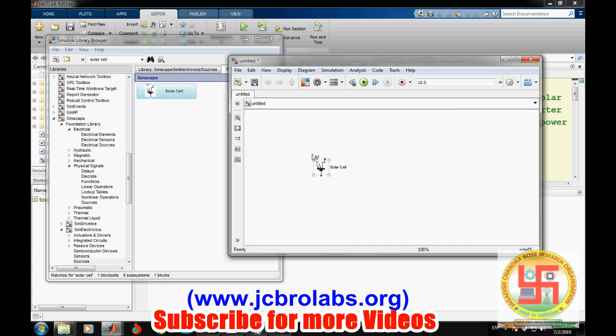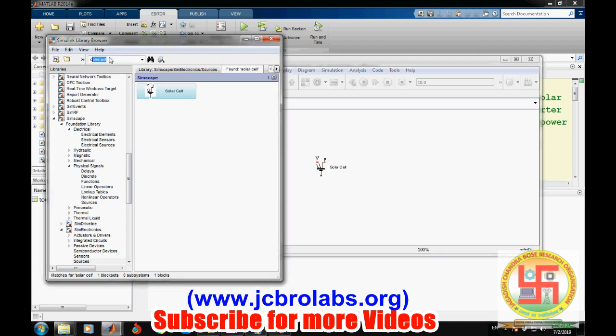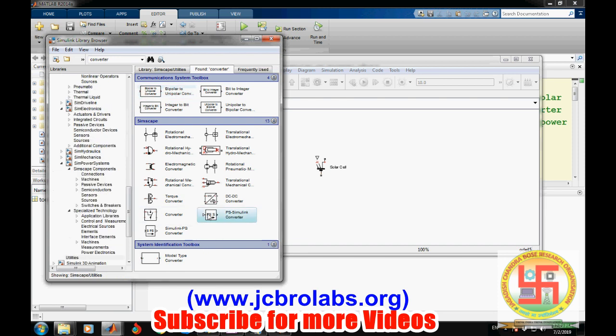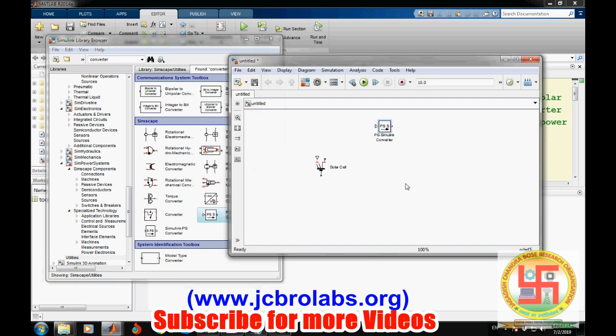So it has three terminals: one is irradiance, one is the positive terminal and the other is the negative terminal. In order to apply irradiance we need a constant. Prior to the constant, let's put some converter, because we are doing a Simscape simulation, so we need a converter from Simscape to Simulink variable. This is known as the PS to S converter, which converts the physical signal to the Simulink signal. These terms are known as physical signal parameters, that is why we need this converter.